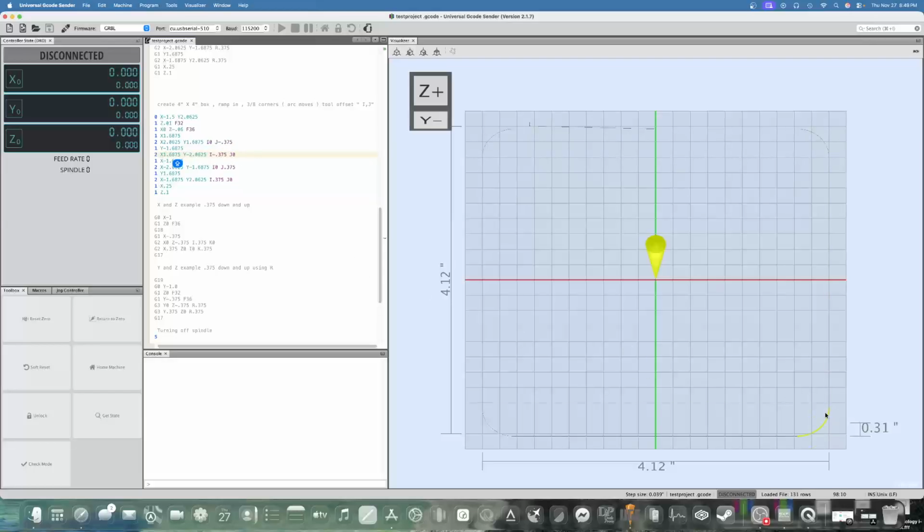And a straight shot. And we're down here on this one. Now this one we're swinging over to the x, so this is going to be on the I. And again, this is facing towards the negative side. So that would be negative 375 on the x-axis, or the I. J would be 0.